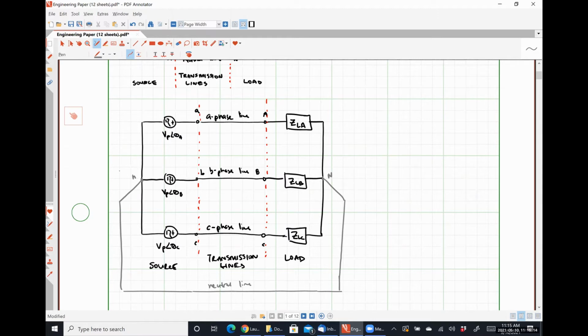And if the motor doesn't vibrate, it's not damaging itself during operation. So we get much more efficient operation of rotating electrical machines like induction motors and stuff like that if we're using 3-phase power. If you're only using single-phase power, there tends to be a little bit of wiggle, and that little bit of wiggle wears out bearings and stuff like that and causes higher maintenance costs.